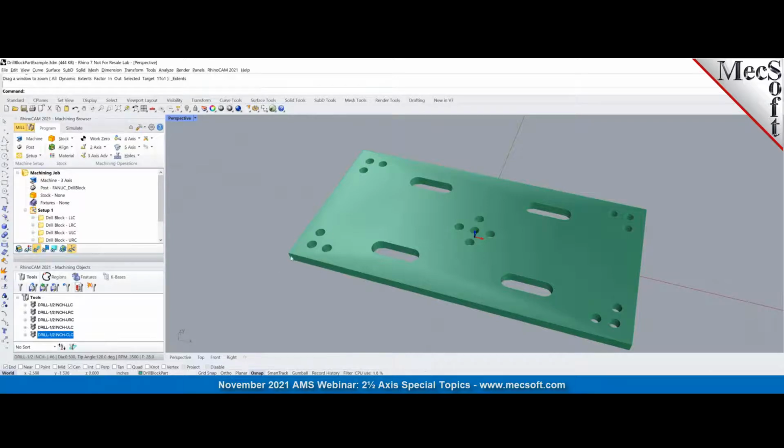So I would need to turn on drills 1, 2, and 3 in my drill block. So what I need to do is go back to my binary table and add the binary numbers associated with these tools, which would be 1, 2, and 4. So that gives me 7. And then I create a tool, it's tool number 7, which I've already done.